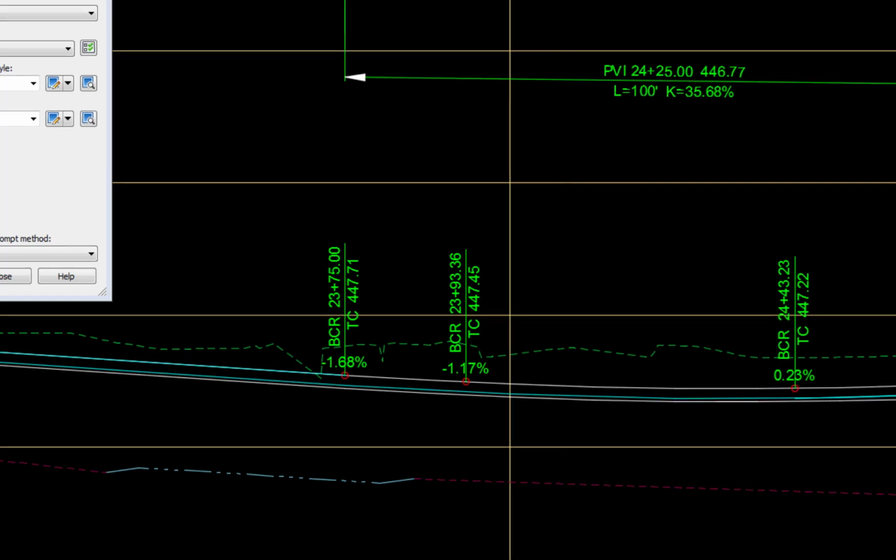A label that contains question marks after it has been created indicates that there is a problem with a label reference. Either the label was created prior to the reference object being created, or the label style was modified to include or change a reference to a Civil 3D object. The procedures to correct label referencing errors are: 1. Pick the label, not the object, to be edited. The Control key may be used to select several similar labels of the same type at the same time.